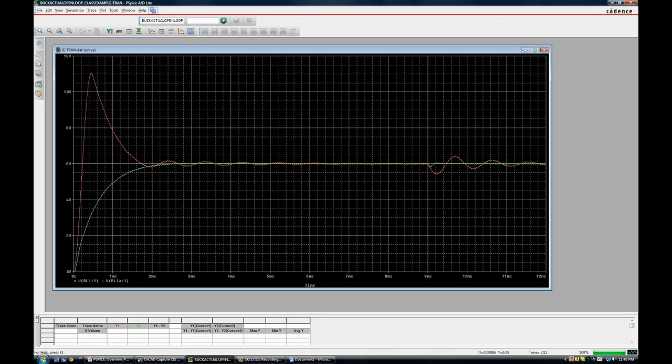When there is a transient at 9 milliseconds, when the load is effectively stepped by 100%, you go from 6 ohms to 3 ohms, you have a long ring, but in the closed loop system, it's a nice, smooth start because of our soft start circuit that's associated with our PWM IC, and then we see the very minor transient due to the closed loop control.